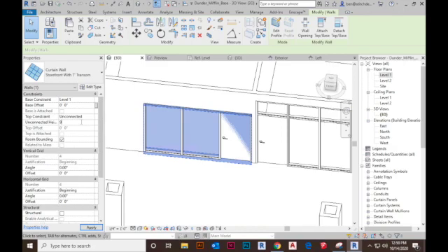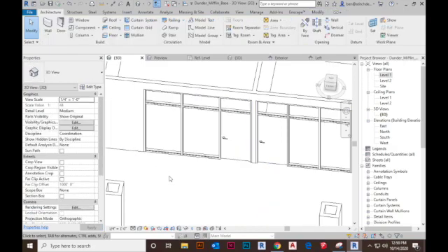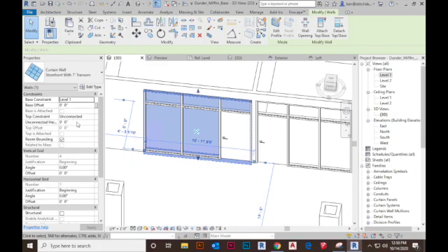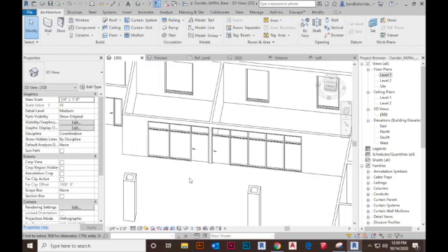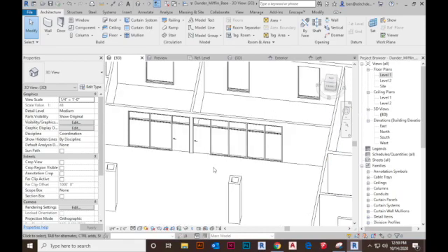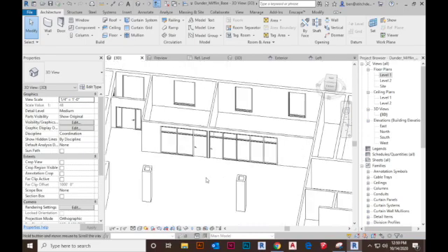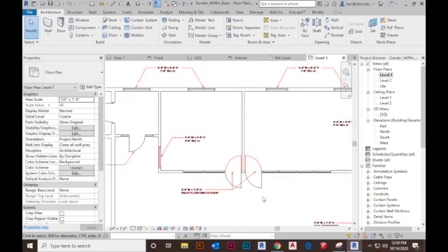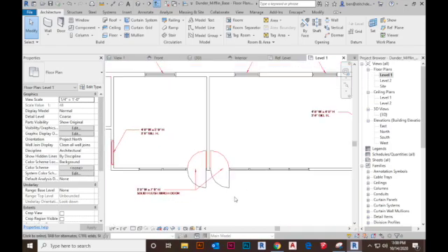So again, it's always good practice to make sure you're checking your properties browser to make sure all of your dimensions are set and that you've checked all the boxes when you start to draw. The beauty is you can always come back and fix it later, like I just did after I drew it without looking. So now we've got the two major storefront walls on the interior drawn. So let's round out this assignment by following our CAD document that we've inserted into level 1 and completing the rest of the storefront openings.